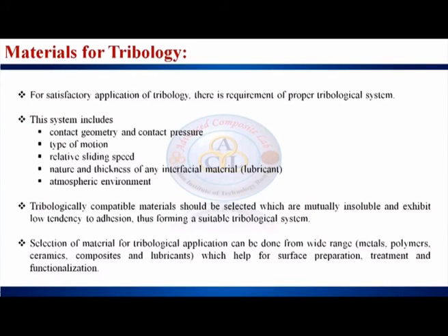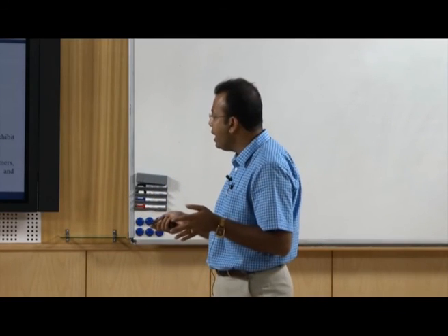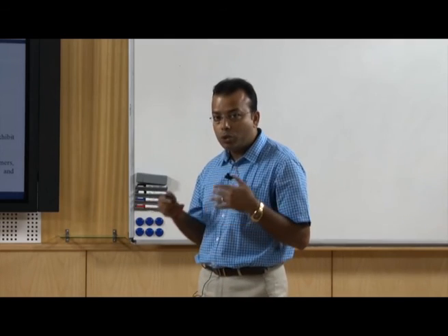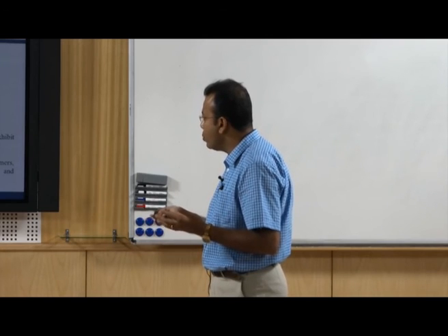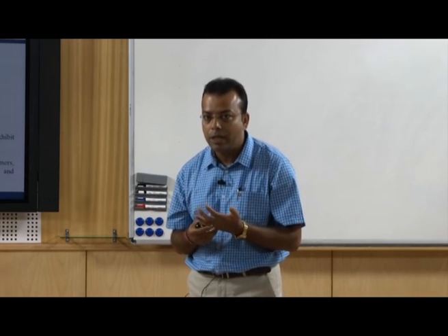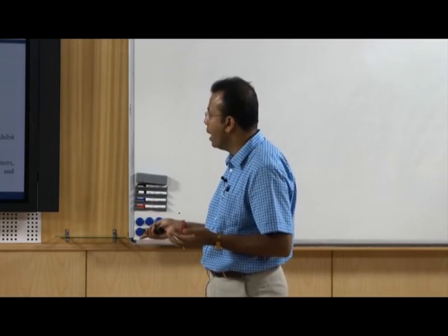Tribology compatible materials should be selected which are mutually insoluble and exhibit a low tendency of adhesion, thus forming a suitable tribological system. Selection of materials for tribological applications can be done from a wide range, like metals, polymers, ceramics, any kind of material which you use in our day to day life. That material can experience tribology. So, to solve this tribological problem, we can do proper surface preparation, treatment and functionalization of that material, so that it will not generate that much friction, heat and wear.